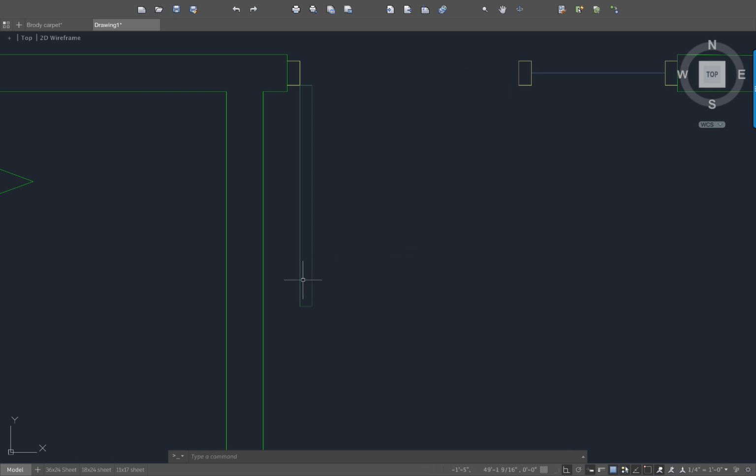Now, the last thing that you want to draw is a dashed line to represent the swing of the door. And the way that you draw that is with an arc. And again, just type in the word arc. As I mentioned, there are no buttons here, so I can't look for the arc command. But what you'd see if you saw the arc command is that there are a number of different ways to draw an arc. The easiest one, the one that is the default value, is just click once on the endpoint, turn off ortho here, once in the midpoint, and then once to finish the arc. Okay. There are, again, a million different ways to draw this arc, and once you've drawn it, you can make certain changes. For example, if I want to make it more archy.